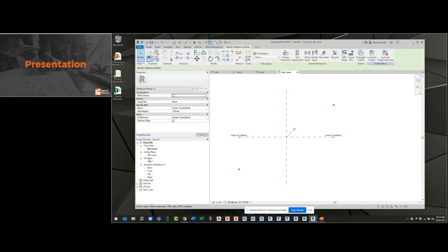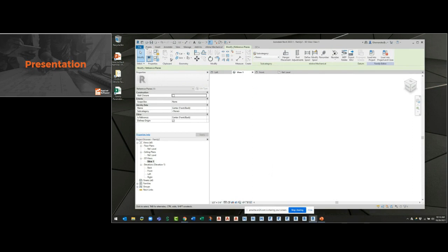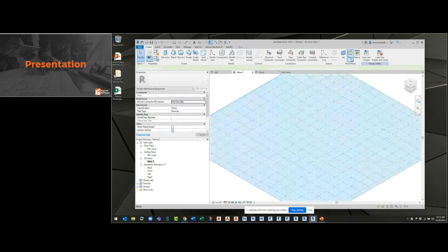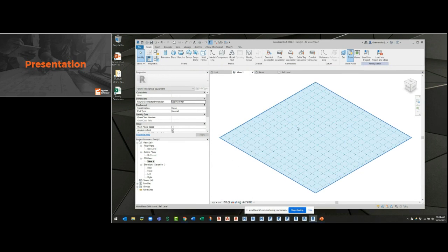Now, what are these things? Well, in an actual 3D view, under the Create tab up at the top, we're going to get into forms and connectors in a bit. But where we usually start off is our helpers, our datums, and our work planes. Okay, I'm going to show the actual work plane that's active. When you start off with the template or a family, you'll see that it's basically the reference level, right? So the floor, digitally or whatever, is the actual work plane. So when I build something, it's going to be built off of this surface.